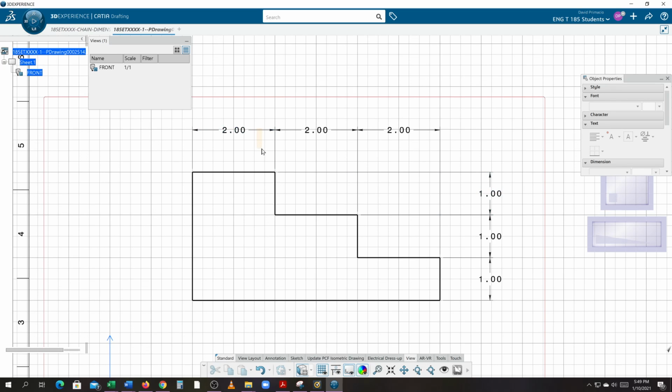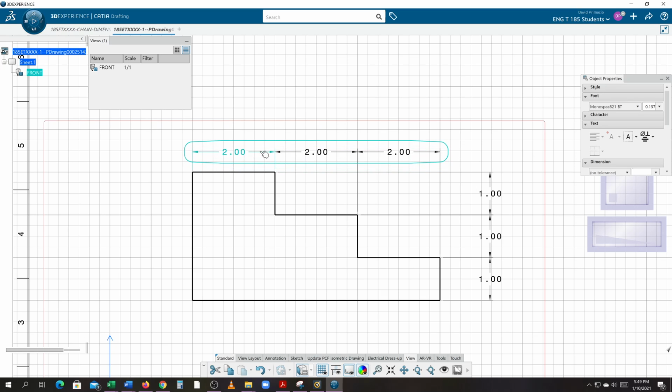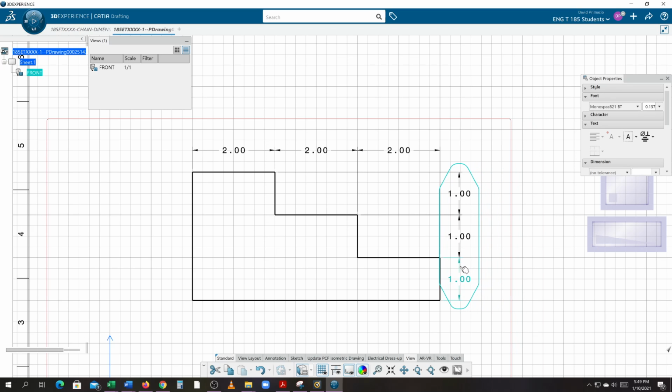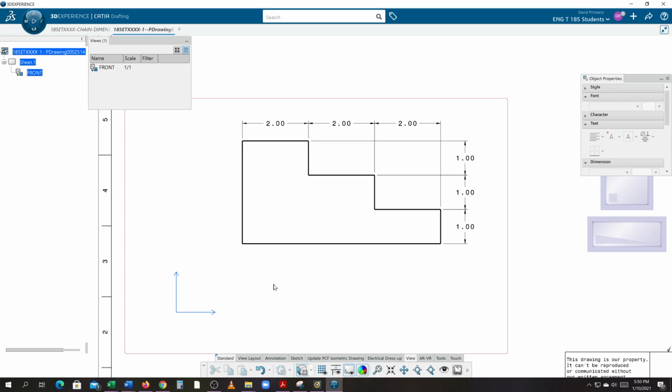This dimension line should be 3/8 to ½ inch off the part. So there's a 1/4 inch, there's a ½ inch. Okay, now the problem with doing that here is, see the numbers? If I go a ½ inch, the one's almost touching it, so I got to back it off even more, like 3/4 of an inch. Turn the grid off, and there's my drawing.